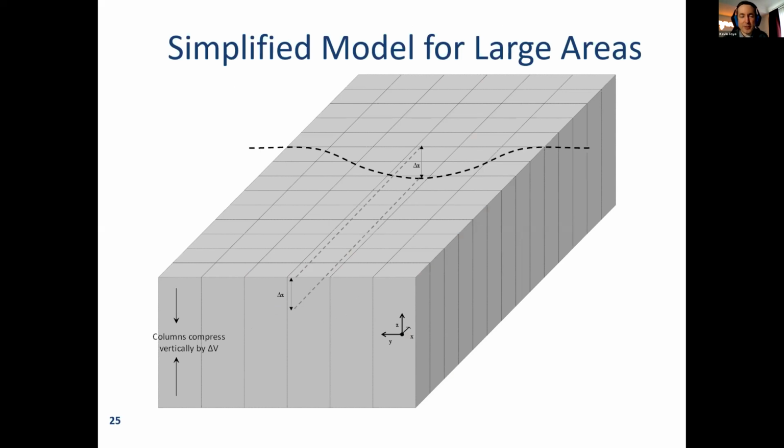How do we go about quantifying the surface depressions over a 25 hectare area? We didn't do it barrel by barrel for 2 reasons. Number one, we don't know where all the barrels are. And most importantly, we don't know in advance which ones are going to collapse and when. And that's why we go to a stochastic or probabilistic approach. To make this manageable as a problem, because we need to do many hundreds of realizations, we made a very simple approach to quantify this.